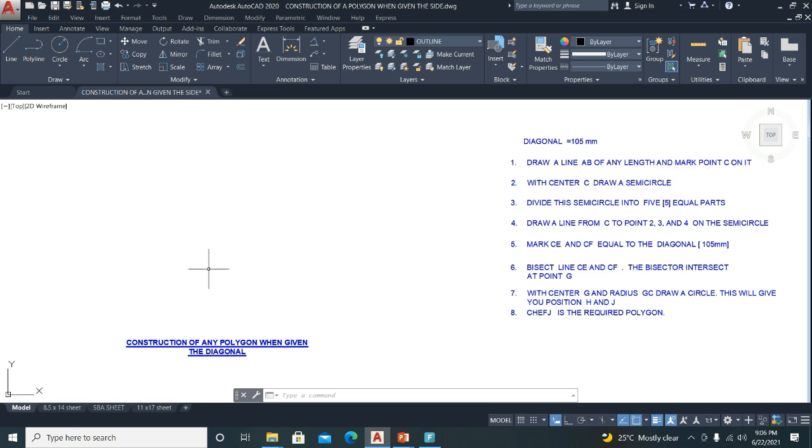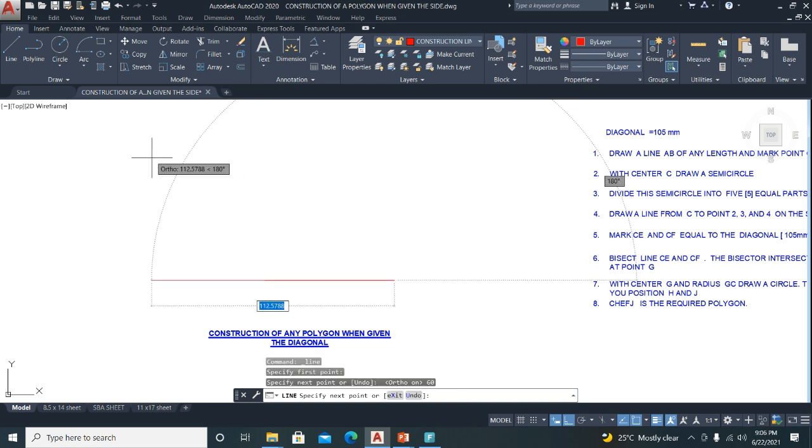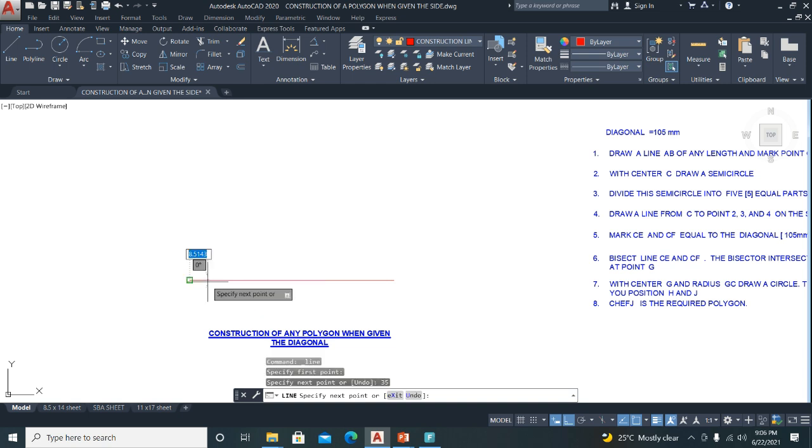Now in order to obtain this, we will draw the line now. Construction line, I want you to draw one line starting about here, so turn on your auto mode, so it will be horizontal. It's going to be about 60, and on this side draw this one probably about 35 maybe. Alright, so you really have two lines here drawn.